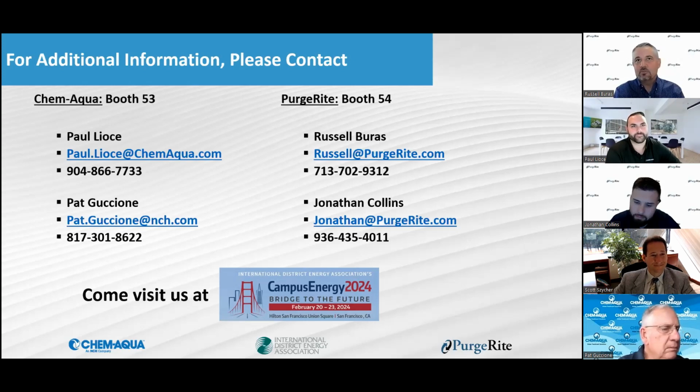So essentially what we see, some people require different things, and engineers and some clients have different requirements. There's times where we will flush through the supply and return, the mains, and we will open up the branches at the very end when it's clean to actually run through the coils. And that's probably the most typical thing that we see.